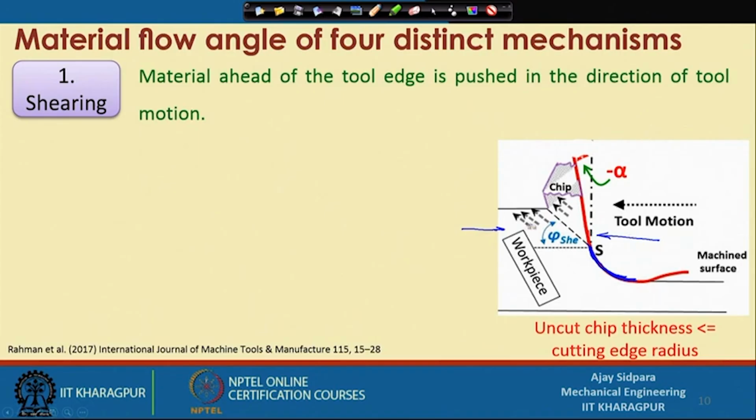Your workpiece is coming from this direction. So whatever material is considered within the zone of HC is going to be pushed in this direction, because now it is not sharp. Your face, that is the rake face, is located on the negative side. If it were in this direction, then the flow of material would be very easy, very facilitated, but that is not the case here.